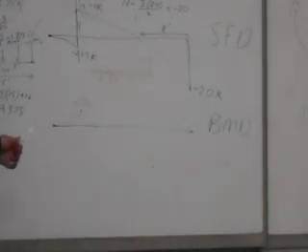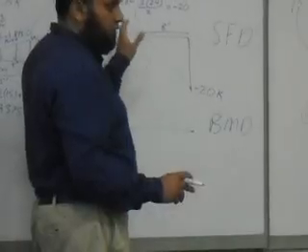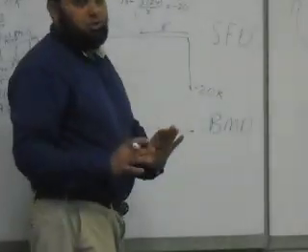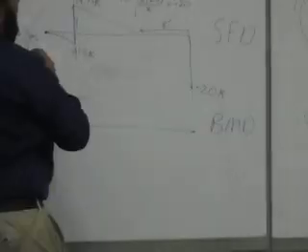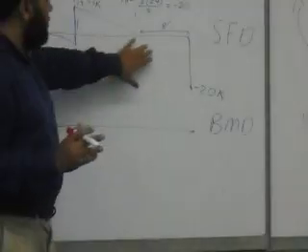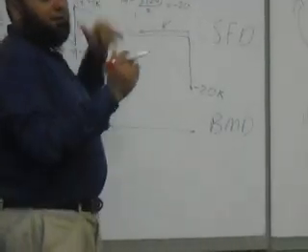You get what I'm doing now? I'm getting the maximum moment. I knew the location of the maximum moment. I knew that this is the zero crossing of the shear force diagram due to this relationship. Fine. So because I know the location here, I'm taking a section at this location and looking at that side. The other option would be to look there. It doesn't make any difference. Even this one is easier because I'll deal with one triangle. Here I deal with a trapezium, which is a triangle and a rectangle I need to divide.